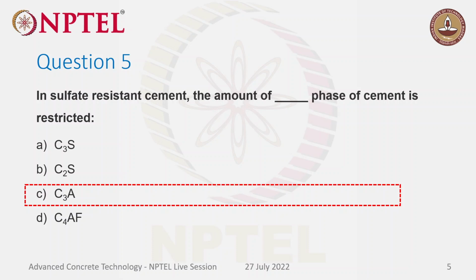So once there is still alumina available in the system, if additional sulfate comes, it can form ettringite kind of phases, which are expansive in nature. If an ettringite type of phase is formed in a hardened cement phase, the expansion in volume will exert pressure and induce stress in the hardened cement phase, which is not helpful.